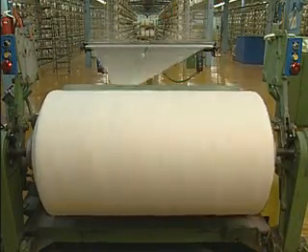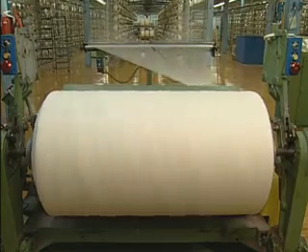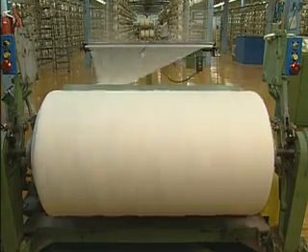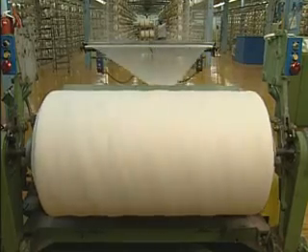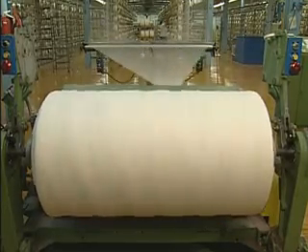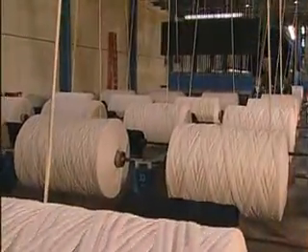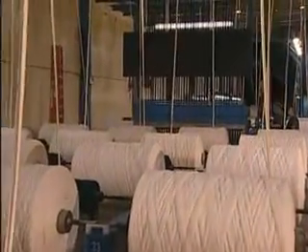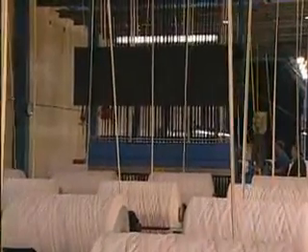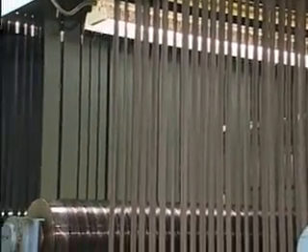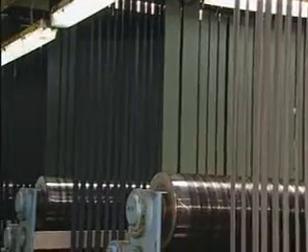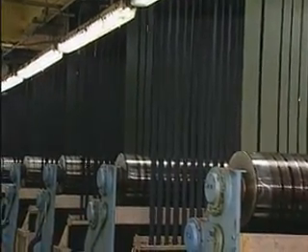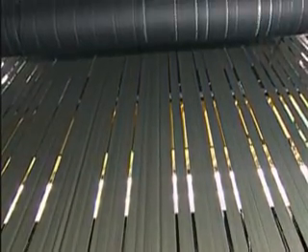By traversing the rope back and forth across the face of the ball, the package is built evenly with constant tension. The ball warps can be from 500 to 25,000 yards in length. They are added together behind the rope dyeing range in a magazine creel to form a dye set. The dye set is always a multiple of the number of beams in the slasher set. For example, if there are 12 beams in the slasher set, there will be 12, 24, or 36 balls in a dye set. The yarn is then unwound from the balls and is passed through the dye range.